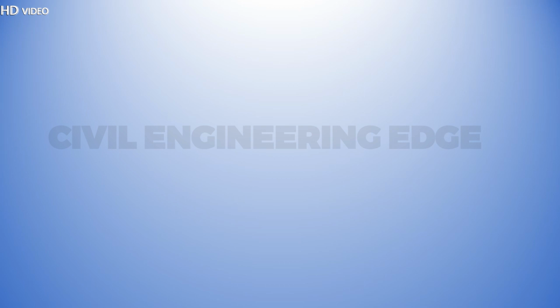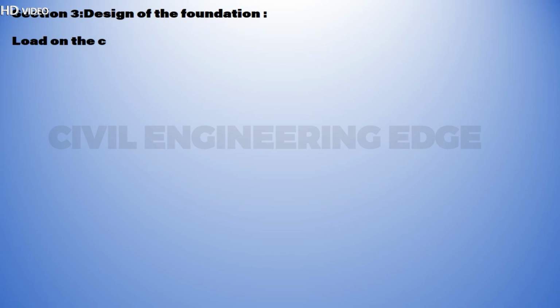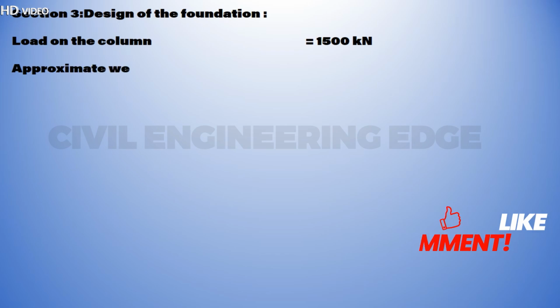Net upward pressure intensity, P = 1500 × 10^3 / (2.75 × 2.75) = 198,347.11 Newton per square meter. Depth from bending moment consideration. The critical section for the bending moment is shown in the figure.